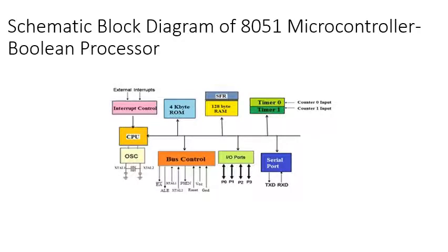Intel developed the 8051 microcontroller in the 1980s. The microcontroller IC consists of standard on-chip peripherals, that is timer, counter, UART, 4 kilobytes of on-chip programmable memory and 128 bytes of data memory.